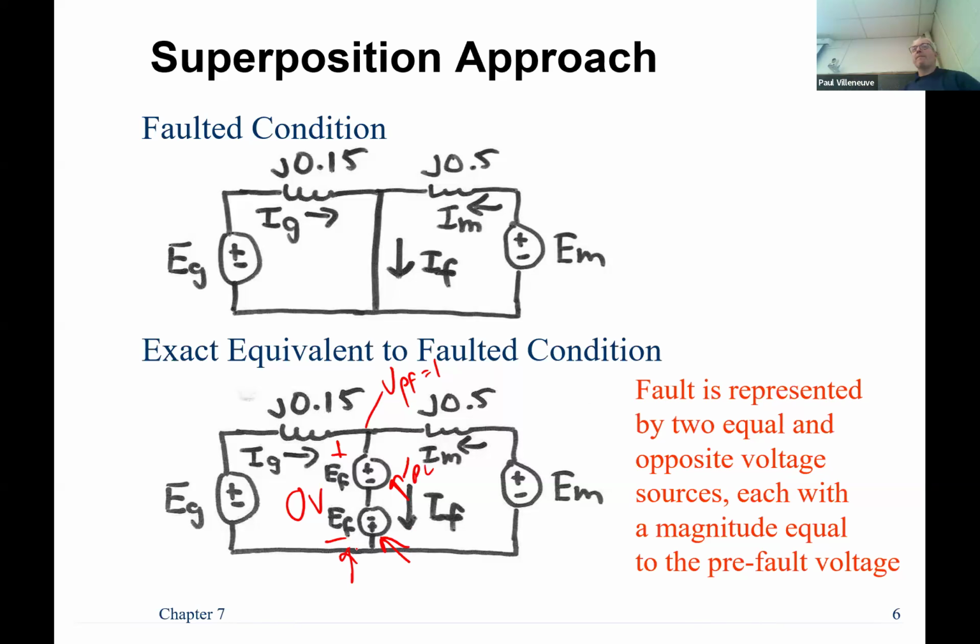Yes, sir. Because when you have to short circuit the supply, right? I'm not short circuiting anything. A short circuit, what's the voltage drop across a short circuit? Isn't that the same thing, when I have those two power supplies in opposite directions? Whether it's a short circuit or not, I get 0 volts. And if I use Ohm's law, V equals I times R, if I get 0 volts, I'm going to get all my current. So it's exactly the same thing as a short circuit. That's the concept of superposition that we're using.